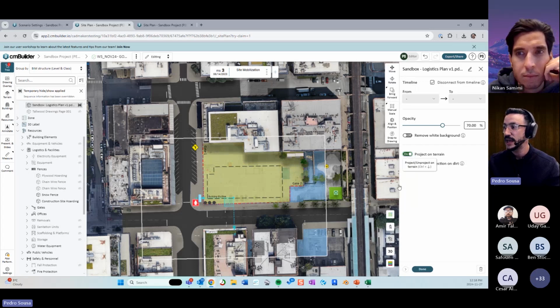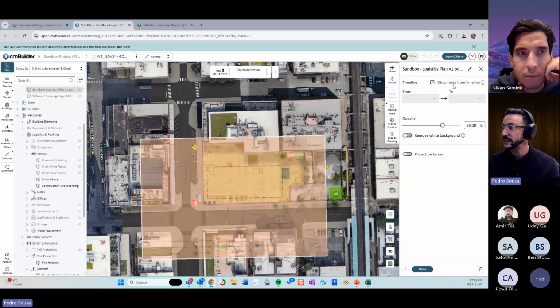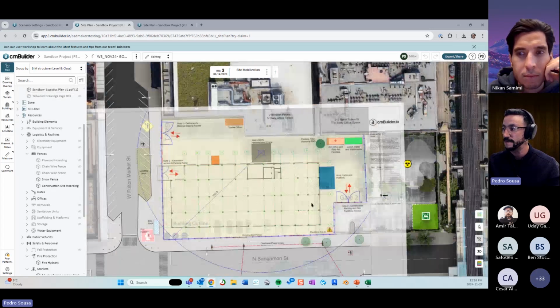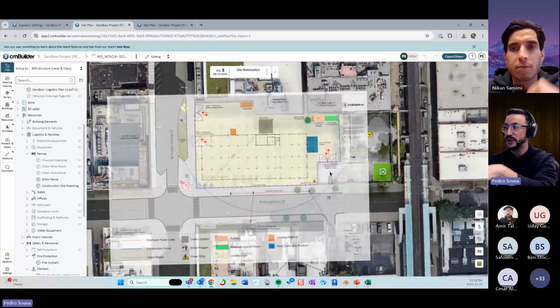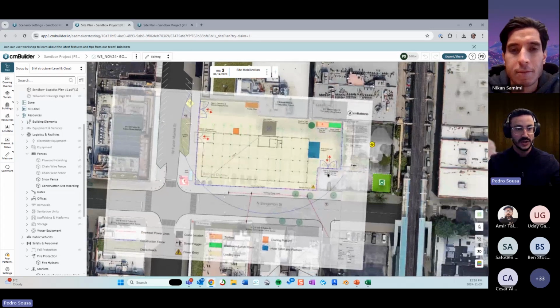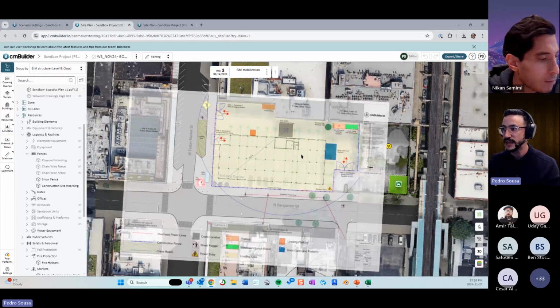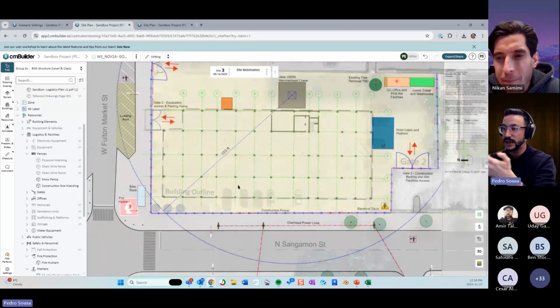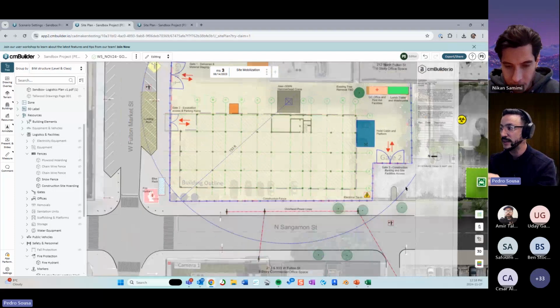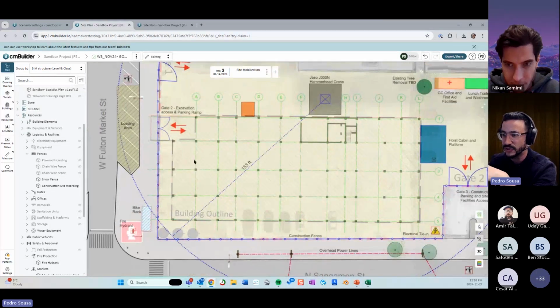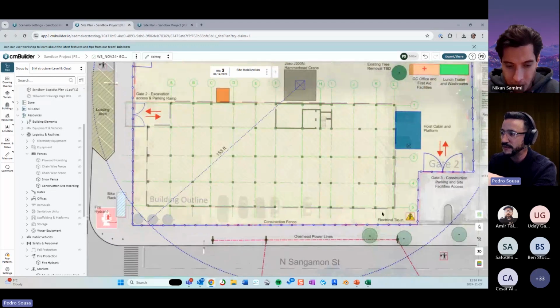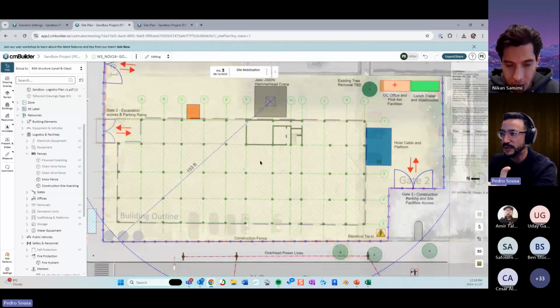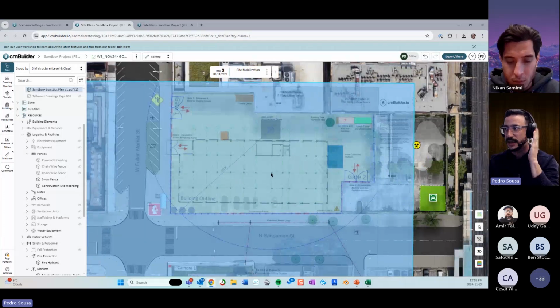So one thing that I can do is to measure this from my drawing. Let's say that I position this drawing in the right spot using my two-point positioning mode. But I want to define a project north that's going to be aligned with the grid lines of this building. You see, the fence itself is not aligned with that. I'm talking only about the drawing, right? So the fence is not aligned with the building. Other things might not be aligned with the building, but I want to use the building as my reference of